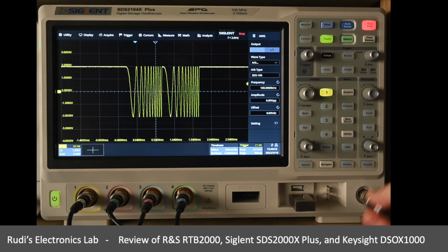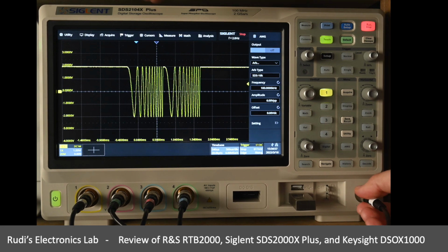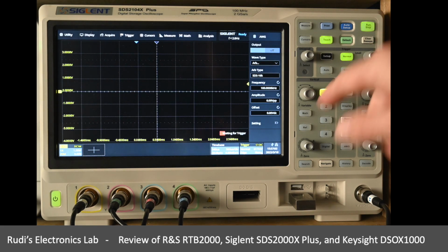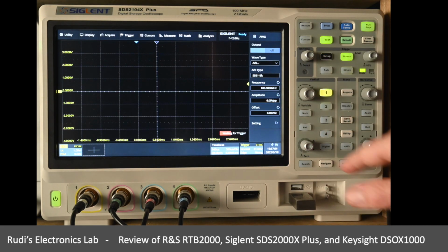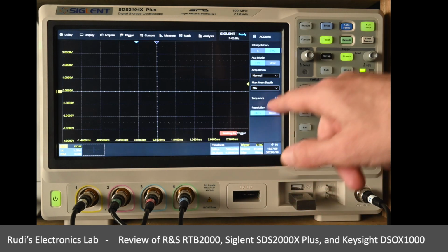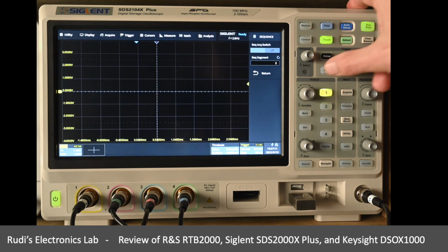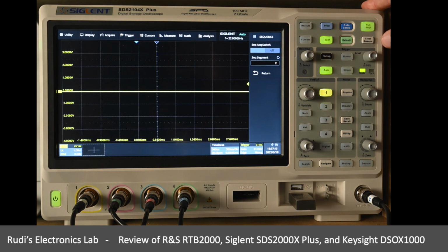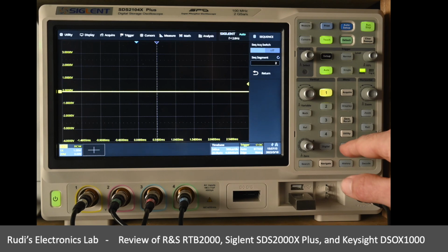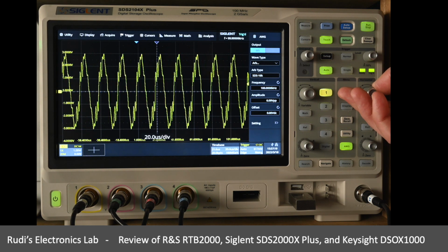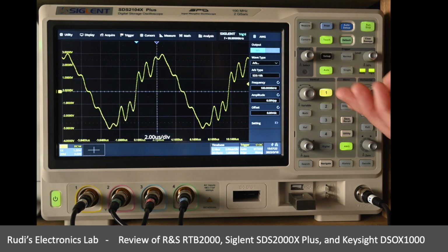Disconnect. Connect it to the waveform generator, and actually get a signal going. Sorry, I now have my acquisition settings all different from the way I wanted them. So I'm going out of this sequence mode again. I'm going to auto mode, and let me see if we can pick up the signal. Is the device off? Ah, yeah, there we go. We're fine. And there we got the waveform that was prepared from the computer.